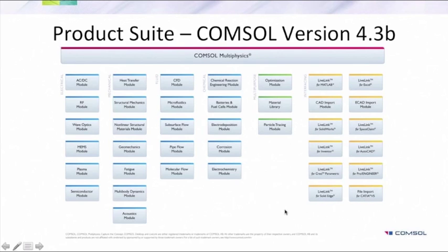However, by using multi-threading, this analysis becomes quite quick because the computation is spread across different processors. Moreover, there is a possibility in the Fatigue Module to perform a combined study where you perform a rainflow counting with Palmgren-Miner. And with the coming release, we will be able to calculate thermal fatigue that incorporates nonlinear behavior such as creep or plasticity.